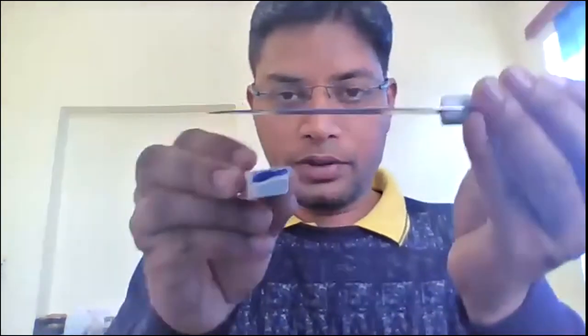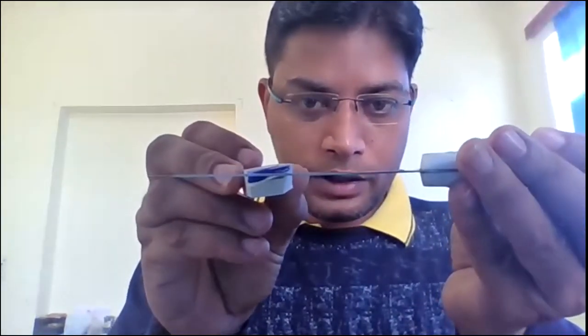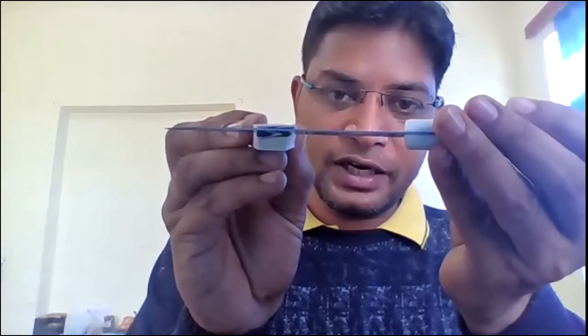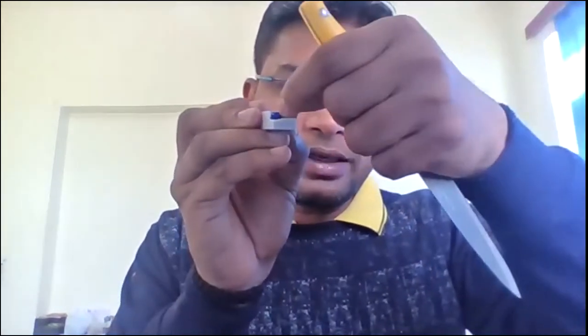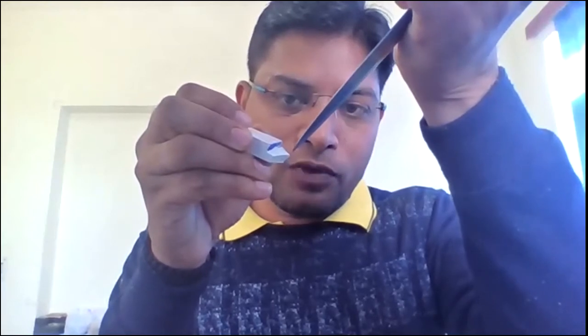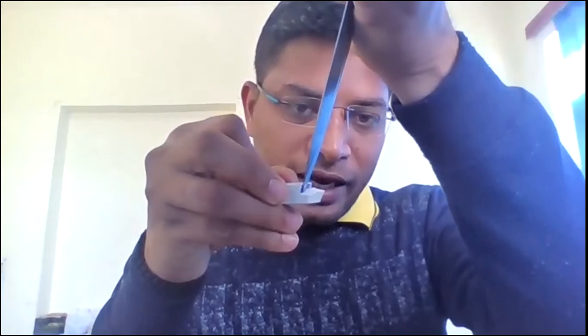I hope now you can see. So this blue color is visible, it means that some angle is created. Now this angle is created on the side, means whatever chip is formed and falls over this tool face will first move towards the back side, and as it enters over here, it will move in this direction. So whatever chip is coming over this tool face will be immediately drawn out from the face area.